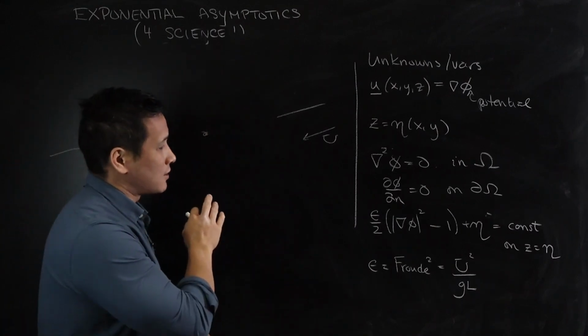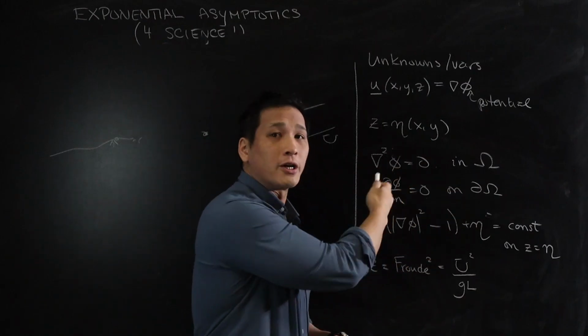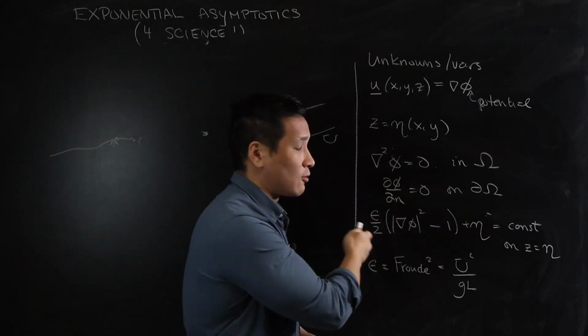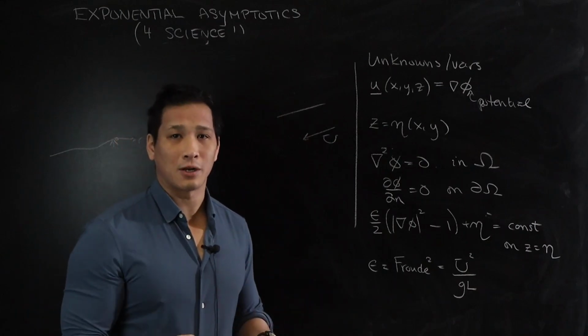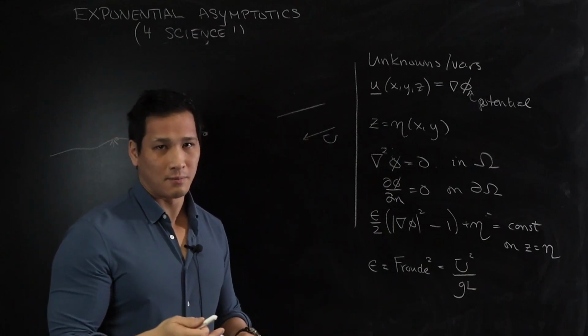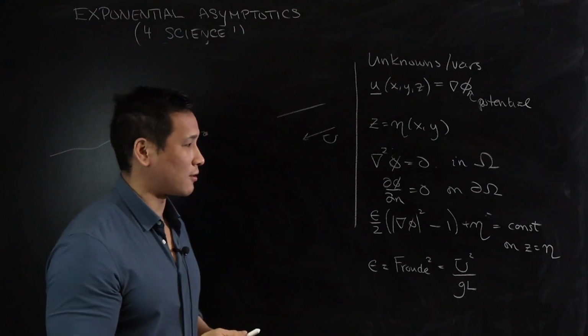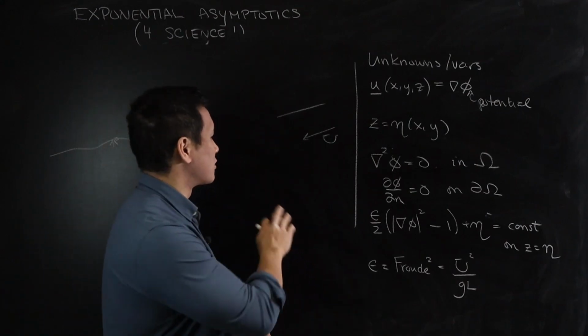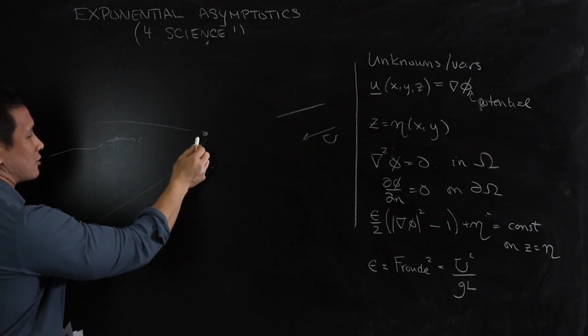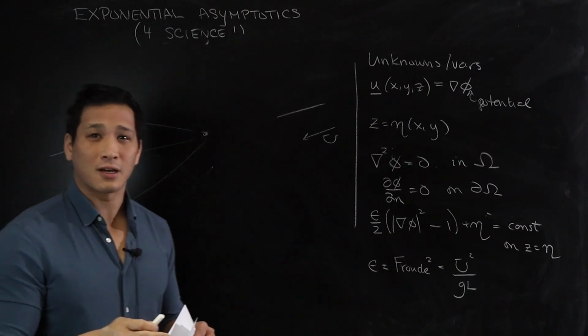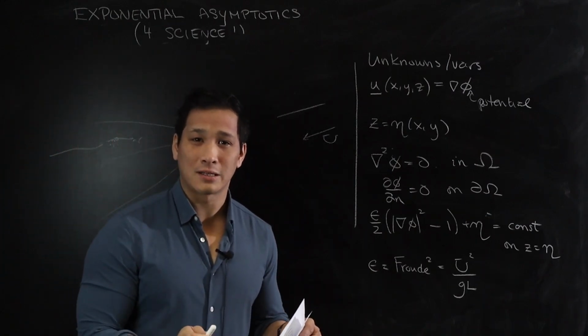And in that case, it turns out that you can then Fourier transform this problem and write down a set of integrals which describe the wave motion. And you can look that up in a classic book on method of stationary phase. So this is one of the methods for approximating integrals. There's a way to develop the wave pattern downstream and show that actually it occurs in this kind of famous V-shaped pattern. This is the Kelvin wave pattern.